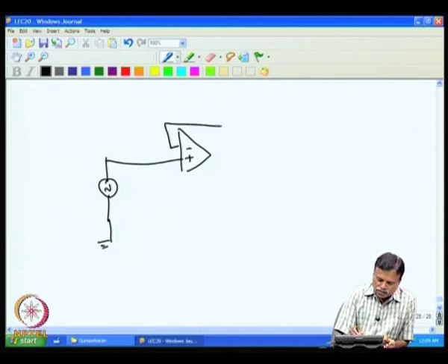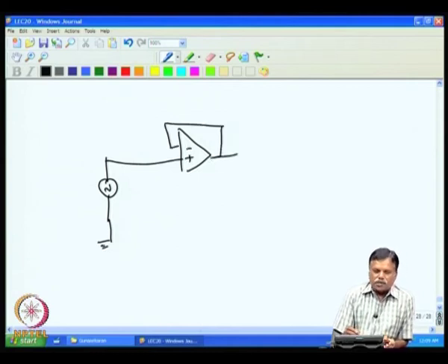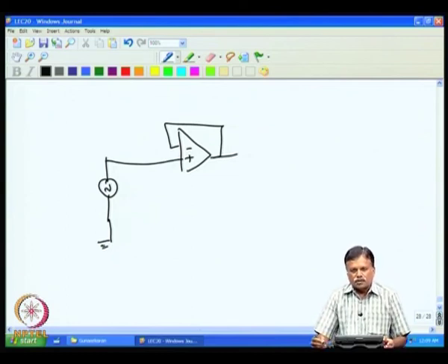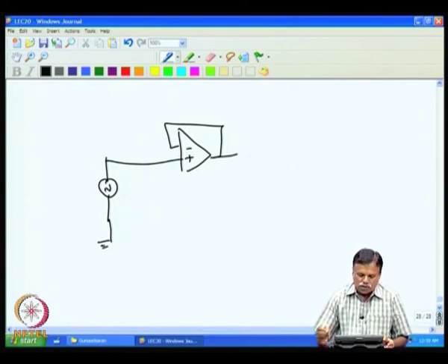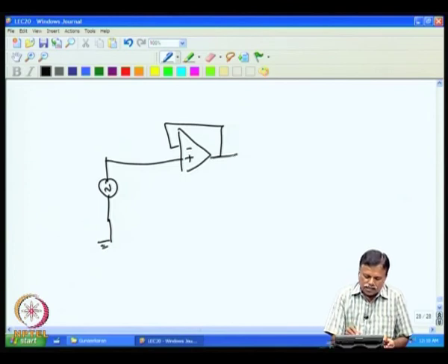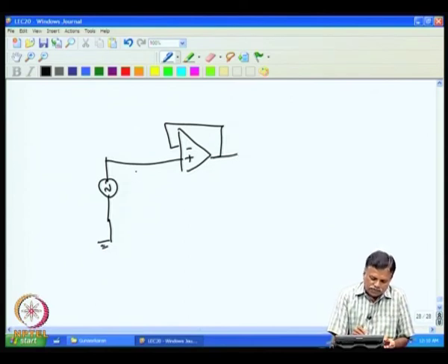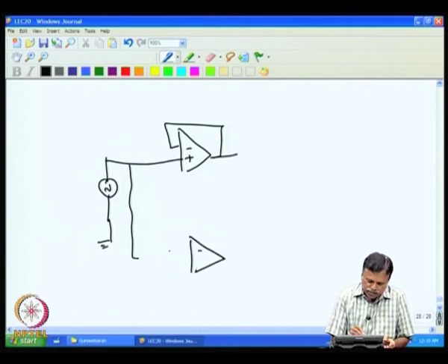Since the output impedance of the op amp is very low, this qualifies like a transformer output, a low voltage, low impedance source. To get 180 degrees out of phase, I give this to another op amp and invert it.